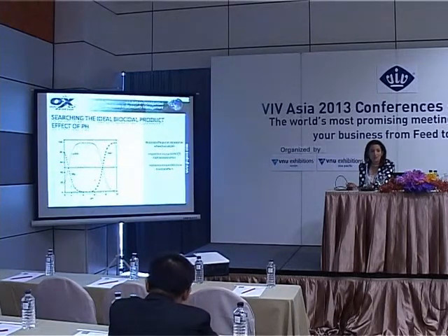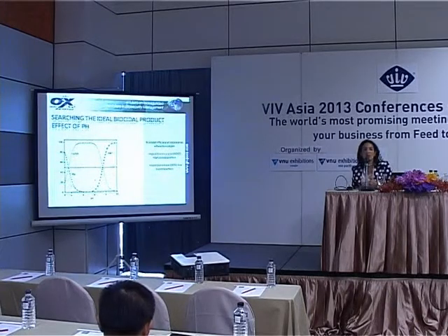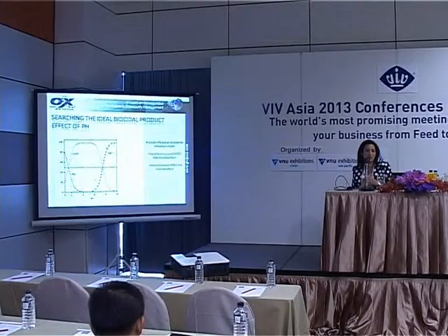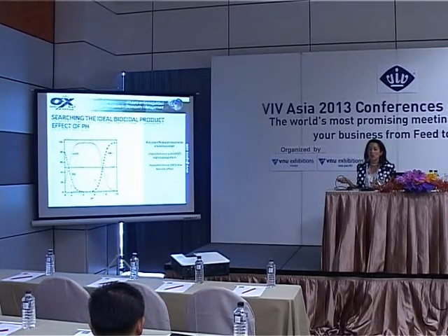In fact, we have a very low biocidal effect. That is why when we have high pH over 7.8, chlorine is not effective, because only hypochlorite ion is formed when the chlorine is in contact with the water. So we could state that chlorine is not effective.